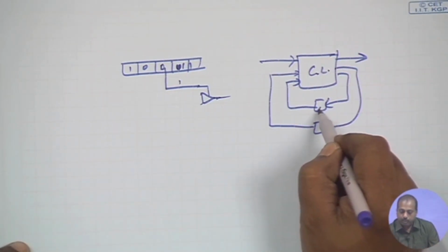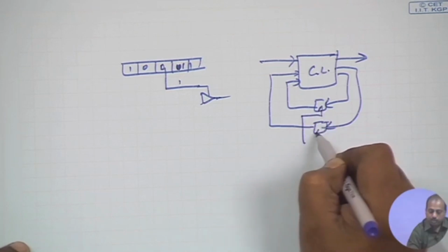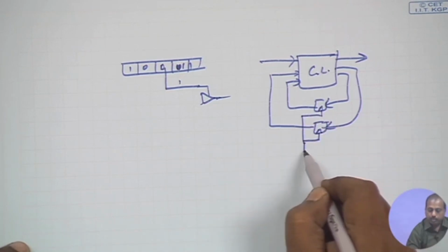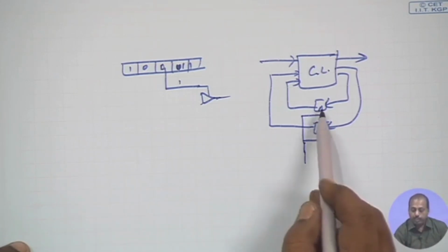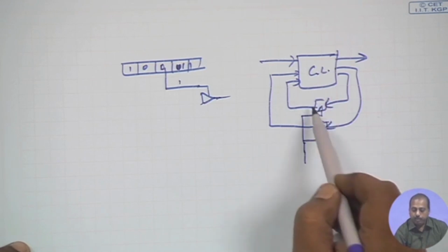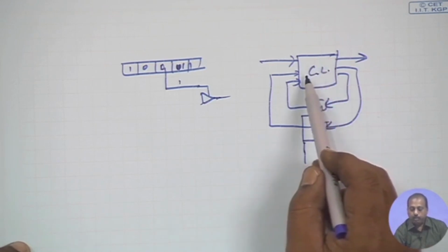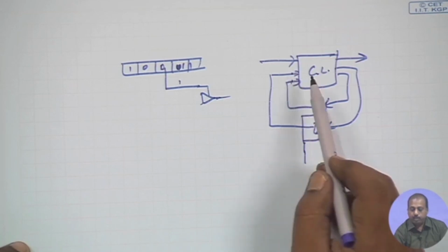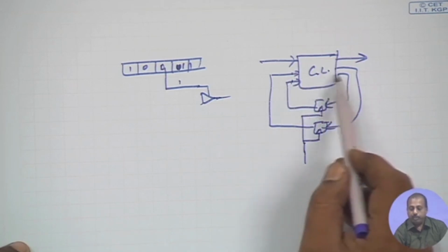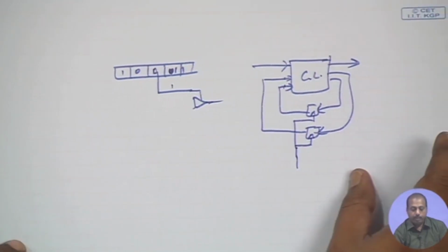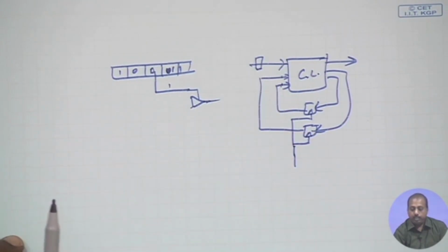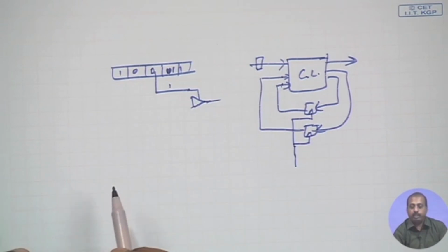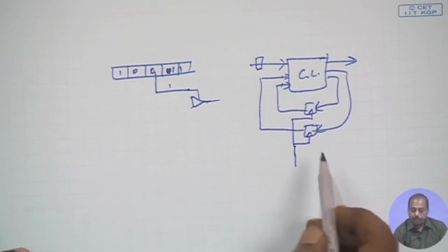what we can do is disable the clock signal that we have, so that these flip flops will not change their values, and if they do not change the value, this combinational logic will also not get any change in the pseudo primary input, and possibly it will not change the pseudo primary output as well. You can also have some sort of latch here to ensure that the primary inputs are also not changing, so that this combinational logic becomes totally idle. Now, this is known as clock gating.